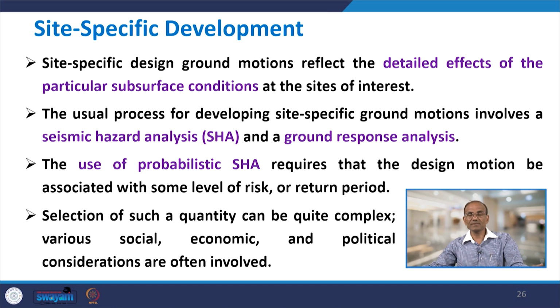GRA we have discussed in much detail, that is one dimensional ground response analysis, or another like two dimensional ground response analysis. So, developing a site specific ground motion will involve seismic hazard analysis, which was also discussed as DSHA and PSHA.